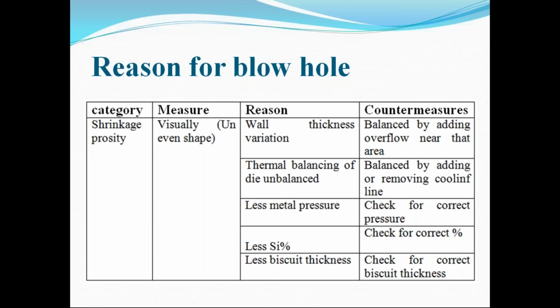Okay, so this is the next one. Now the next one, this is the metal pressure. When molten metal is still held in the die, extremely high pressure is applied. Okay, we apply this pressure by means of the plunger. So this is called the intensification pressure. Okay, so this high pressure compresses any gas entrapped in the metal and feeds additional metal into the cavity to compensate for the shrinkage of the metal as it solidifies. Okay, first it compresses the liquid material, and also if there are some cavities available, due to this compression, they can be removed.